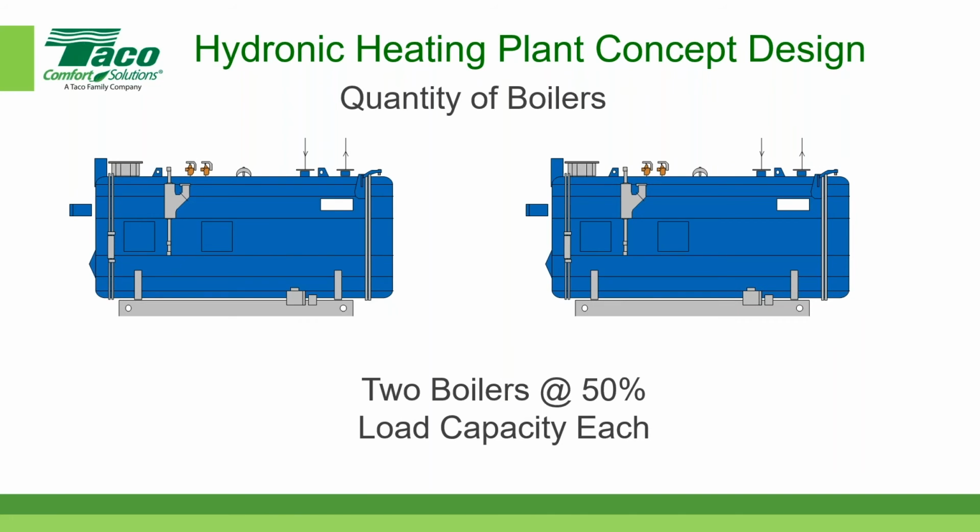Another possibility is two boilers at 50% each. The concept here is that if one of the boilers should go down, you do have the second boiler, and for a significant portion of the time, one boiler at 50% will keep the building at least warm enough to accommodate on a mild winter day full occupancy and functionality of the building. And certainly at night, it'll keep the building warm enough so it doesn't freeze.